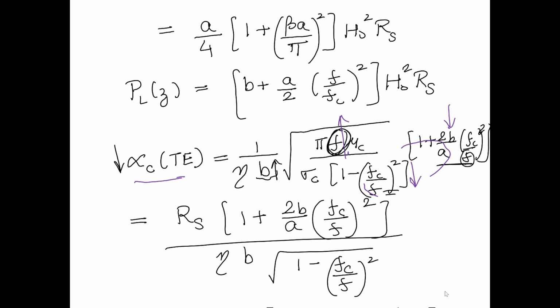With an inner conductor, you have a huge current density on the inner conductor, and as you go to higher and higher frequencies, those inner conductors start to create a huge loss. So when you're working at a gigahertz or even a few gigahertz, coaxial cable with the inner conductor works well. However, if I'm now operating at a few tens of gigahertz, the loss of that coaxial cable would be just too much for me to bear.